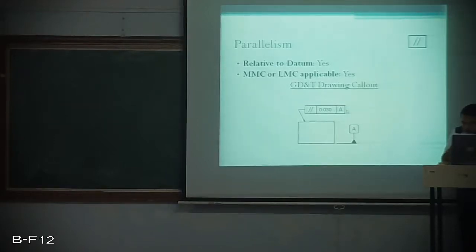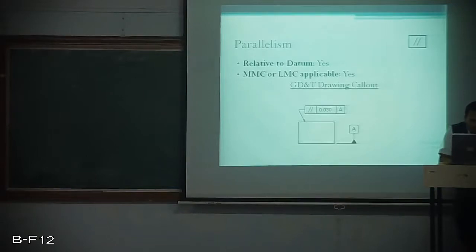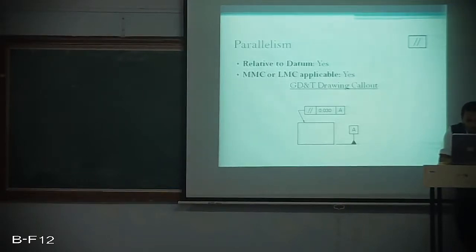But previously in the form tolerances only the dimension symbol block and followed by the tolerance block were mentioned, but over here in case of orientation symbol we are using three blocks, one block for the symbol and one block for the tolerance specification and another block for the datum specification.